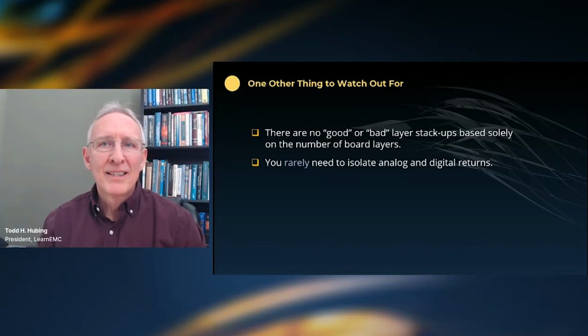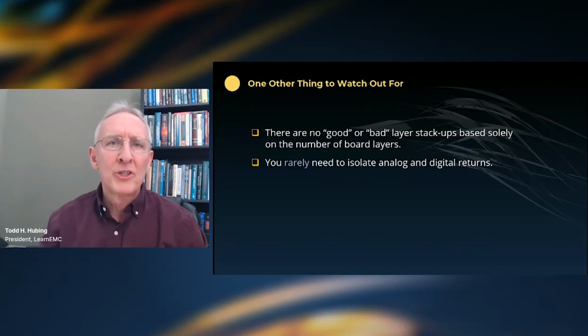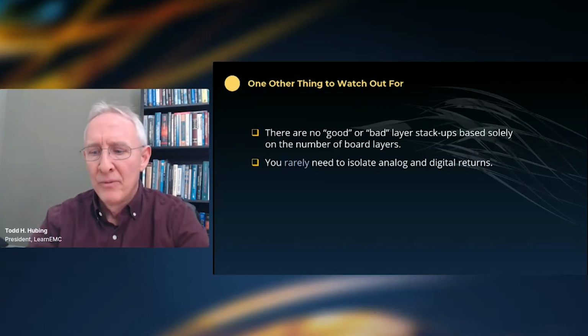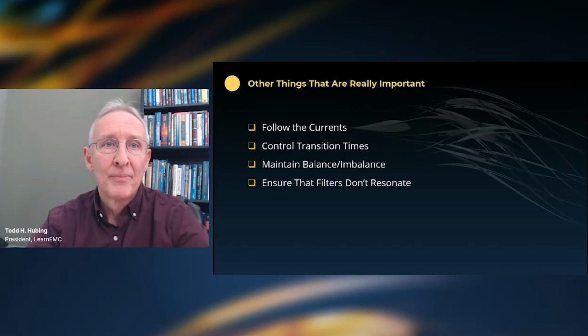Also, you rarely need to isolate analog and digital returns. If you're doing that, make sure you understand exactly why you're doing it and make sure it's necessary. Generally, we should have one solid ground plane that acts as our current return for everything high frequency anyway.